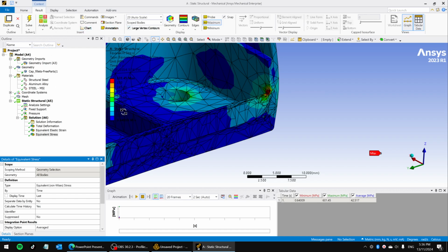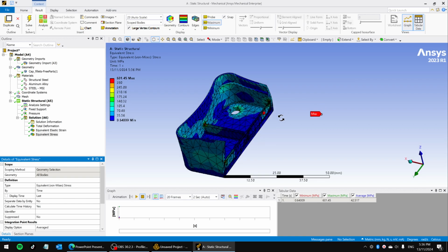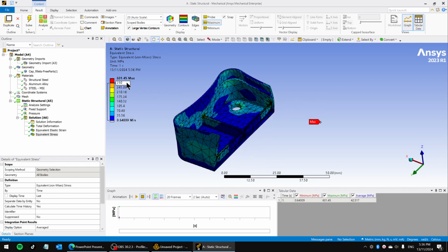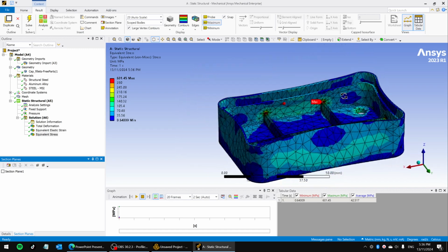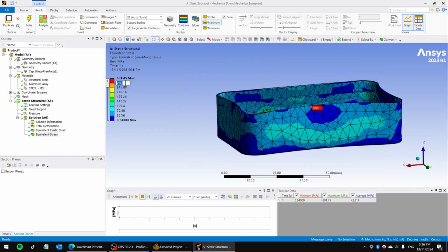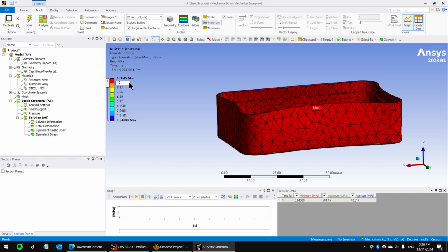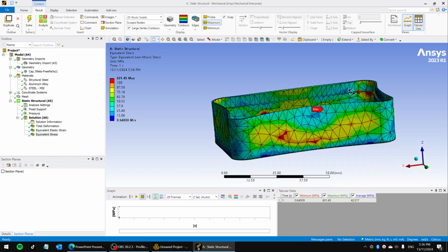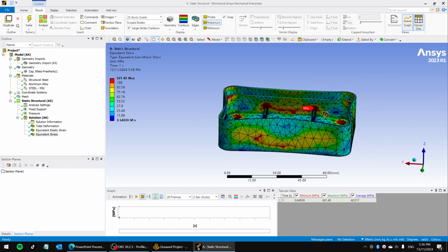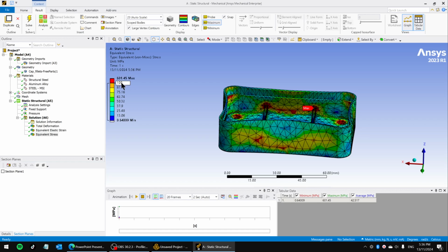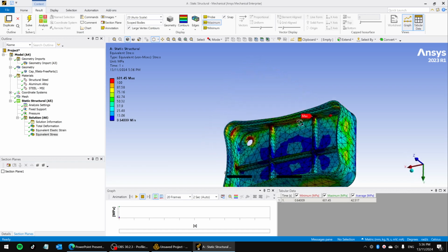What else? We need to determine whether this thing is having problem or not. So if you look at 280, you're not gonna see much. You can see some more if you change this one to lower. For example, you go to 100, and everything is red. 100. Now you can start to see locations of high stress. So you have to play around with the values of maximum, not maximum, the second one. Can this be dragged? So this is a better representation of the problem.